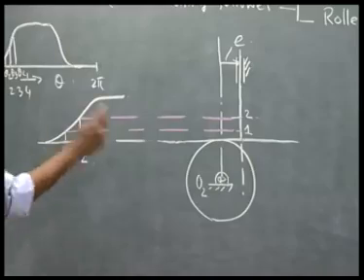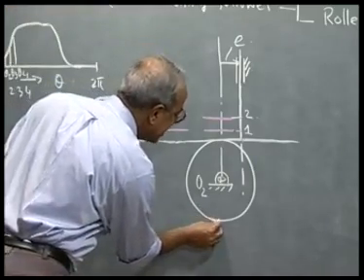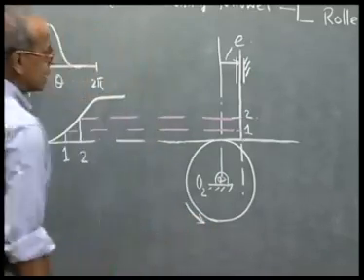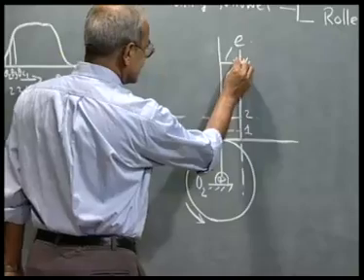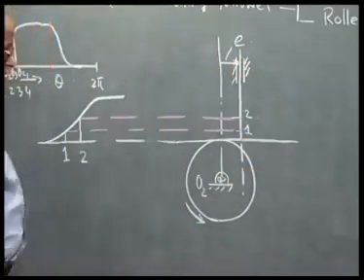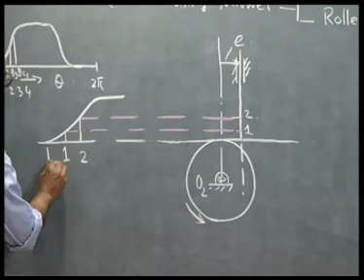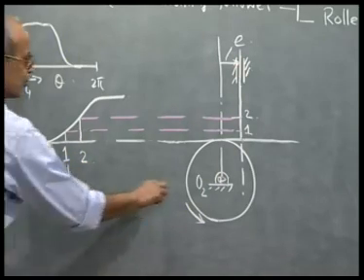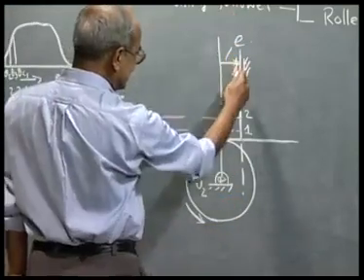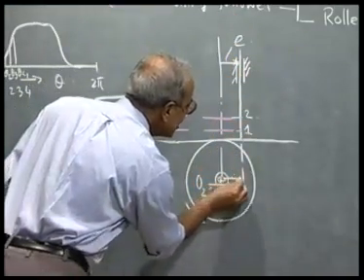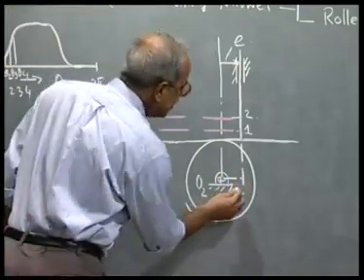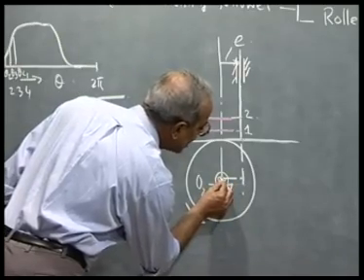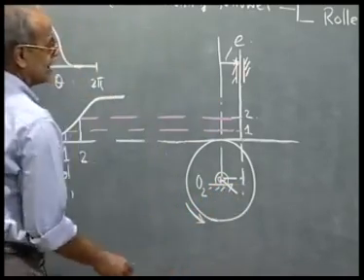To obtain the cam profile, as we have done in the analytical method, we hold the cam fixed and make a kinematic inversion such that this fixed link rotates in the opposite direction. Suppose for station point 1 the cam rotation is theta 1 in the counterclockwise direction. The kinematic inversion is that the follower axis must rotate by the same value of theta 1, but in the clockwise direction.